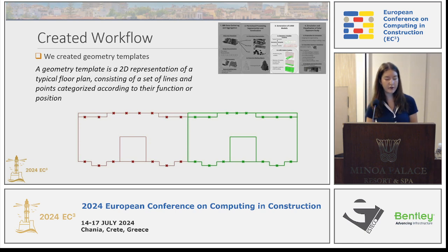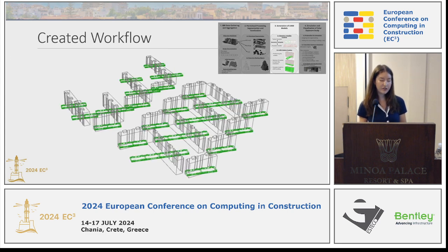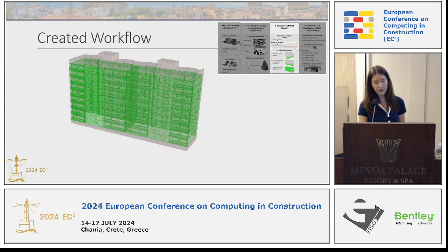On Rhino, it looks something like this. And then from this, knowing the number of staircases, we can create the actual floor plan of the building. Then we match these created floor plans to the LOD2 level geometry, rotate and fit it inside the existing geometry, and then basically copy it up in a number of the floors.